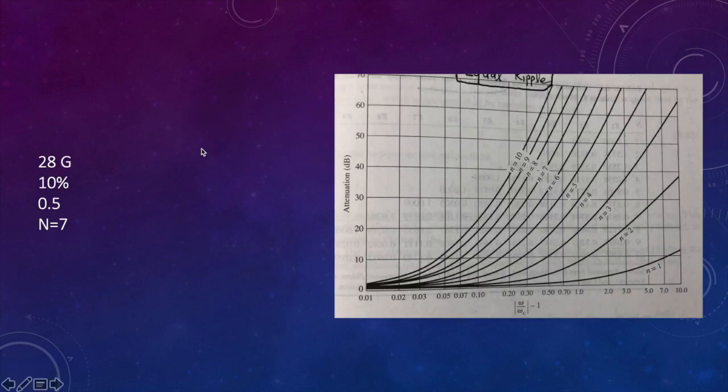In this example, we want to design a bandpass filter. The center working frequency is around 28 GHz, and the fractional bandwidth is 10%. The prototype is an equal ripple filter. Why do we choose an equal ripple filter? For an equal ripple filter, it attenuates much faster in the stop band compared with the maximally flat one. So we use the equal ripple filter.